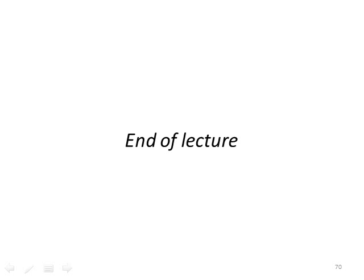Okay, so that is the end of lecture number 6. I recommend that you go through the example at the end to make sure that you understand the numbers that I've given to each one of the blocks for the sensitivity and also for the uncertainty value, which is the standard deviation. And very importantly, this concept of taking the uncertainty for each of the measurement sources and then being able to add the variances, which are the squares of the uncertainty of each of the individual components, to look at the overall uncertainty in the system.